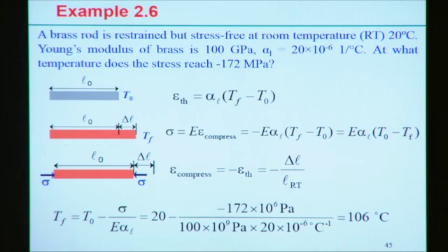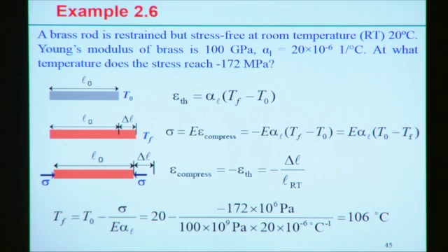If we look into the third figure, if the material is constrained, or resists deformation due to the temperature change, then definitely it will create some amount of stress. The third figure indicates that some amount of compressive stress will be generated if we try to restrict the elongation or deformation in one specific direction. So that thermal strain is useful to estimate the amount of stress here.